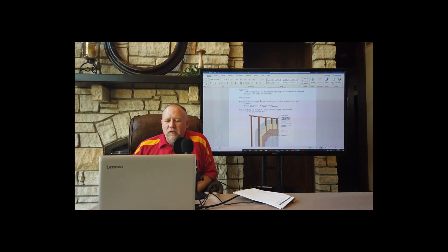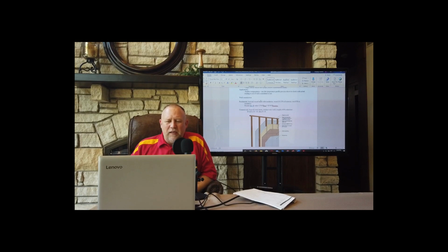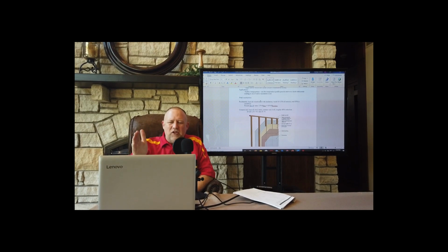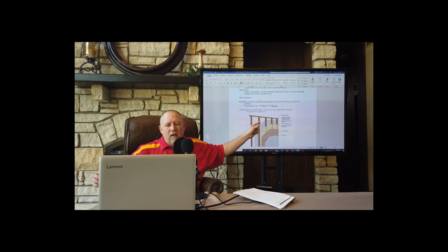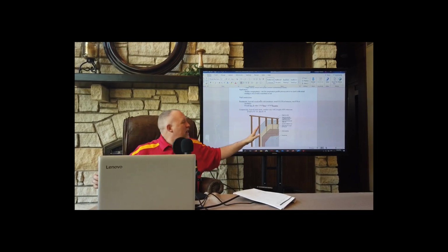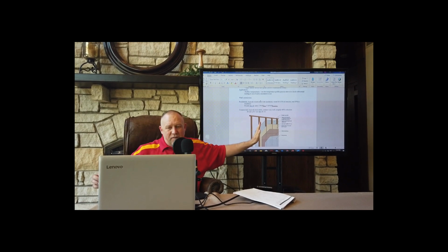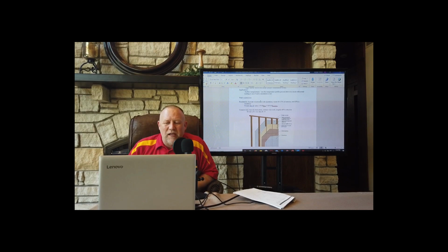So when we do the heat transfer calculation, you just figure up the R value through the insulation, and then do that as a composite wall, do the R value through the wood, and then whatever that total area is, let's say this was 100 square feet of wall, then 15 square feet of it is actually wood stud, and 85 square feet of it is insulation. And then you can do the heat transfer that way.